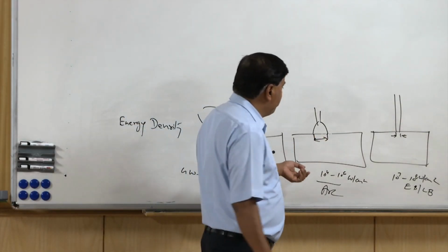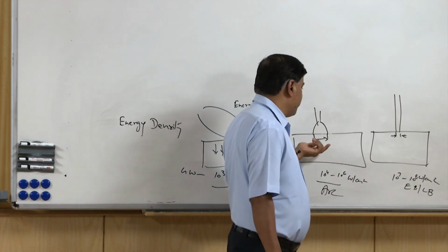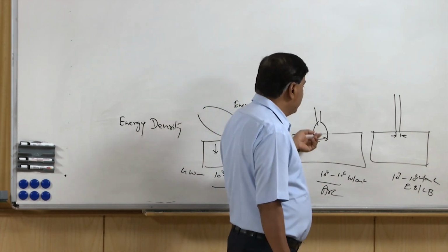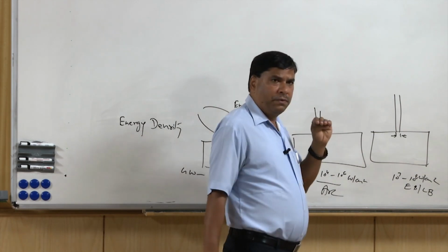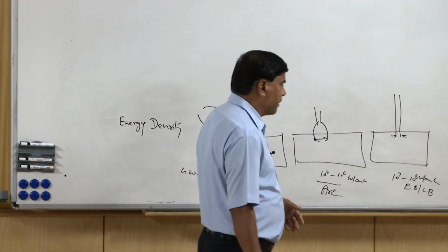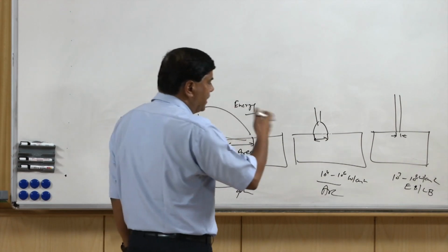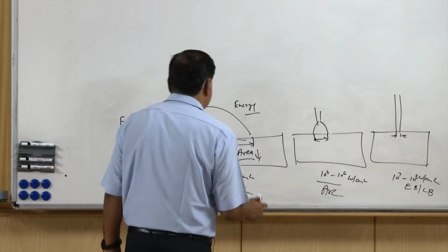The smaller the area, the less heat will be dissipated to the underlying base metal, and the less time it will take to fuse. So the amount of heat to be delivered for fusion keeps on decreasing with increasing power density or energy density.